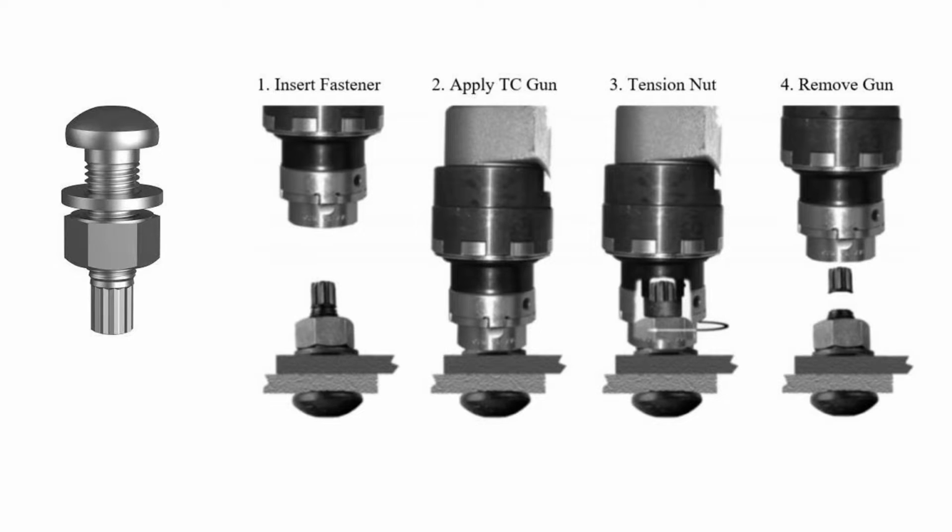The third method is to use twist-off type bolts. These are specifically designed bolts that must be installed with specially designed power wrenches. The bolts have splined ends over which an inner socket of the wrench fits. As the outer socket tightens the nut, the inner socket turns the splined end of the bolt in the opposite direction. The wrenches are calibrated for the size and strength of the bolt, and when the required tension is reached, the end twists off. This makes inspection of the installation particularly easy.